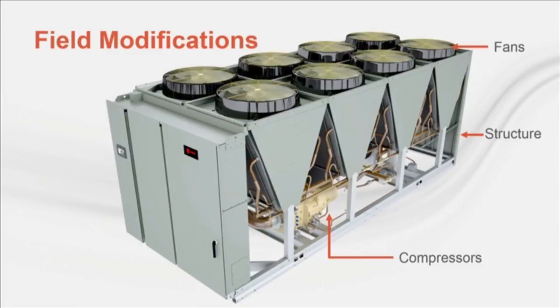In most cases, the HVAC equipment manufacturer won't have sound data to show the contributions of individual components. For example, suppose the unit has fans and compressors with an enclosure to quiet the compressors. Without knowing the relative contributions of the compressors and fans, there is no way to know how much the enclosure will reduce the total sound.